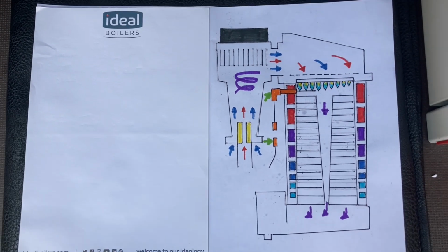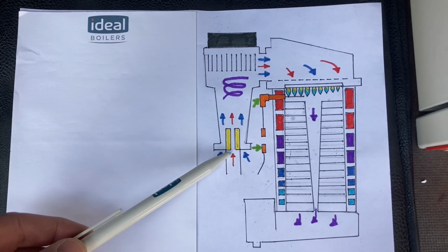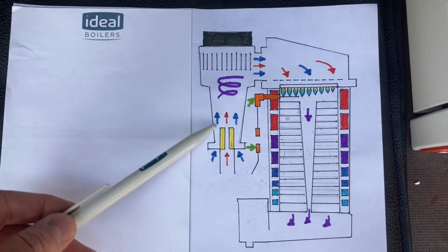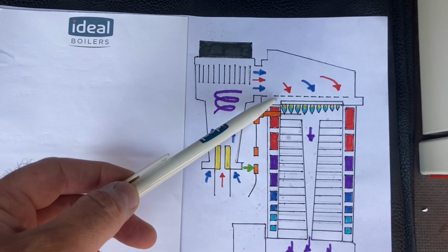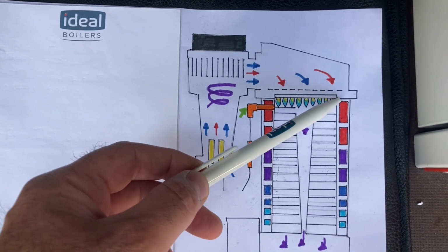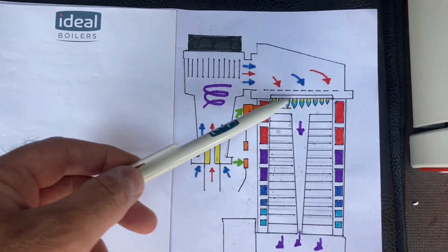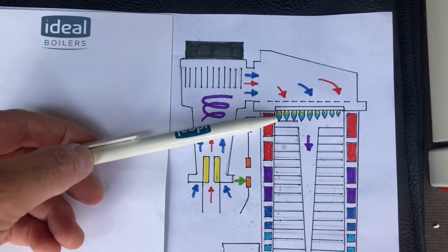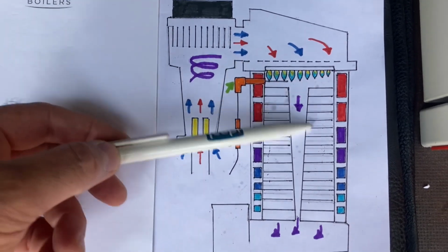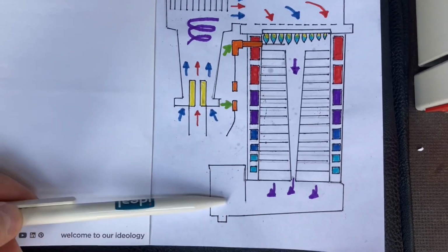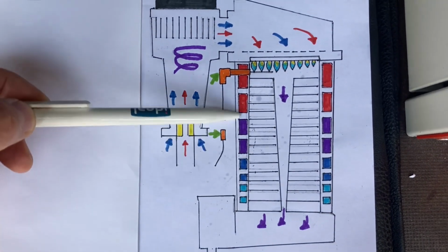So I've drawn a picture here. This is the gas inlet to the fan, the injector. This is the Venturi, the fan. This is the burner here. This is the baffle plate. This is the ceramic plate. This is the gas flame indicator, full burner into minimum burner. This is the heat exchanger, sump, flue manifold, condensate. These are the waterways within the heat exchanger.